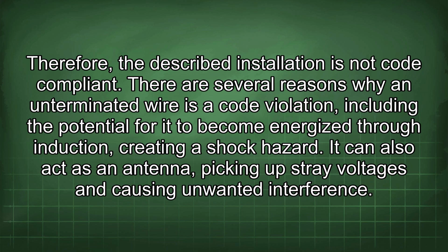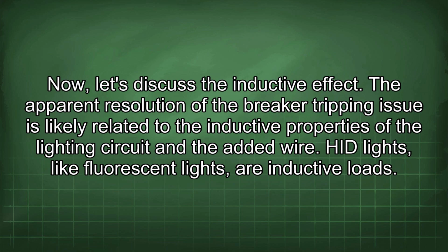There are several reasons why an unterminated wire is a code violation, including the potential for it to become energized through induction, creating a shock hazard. It can also act as an antenna, picking up stray voltages and causing unwanted interference. Now let's discuss the inductive effect.